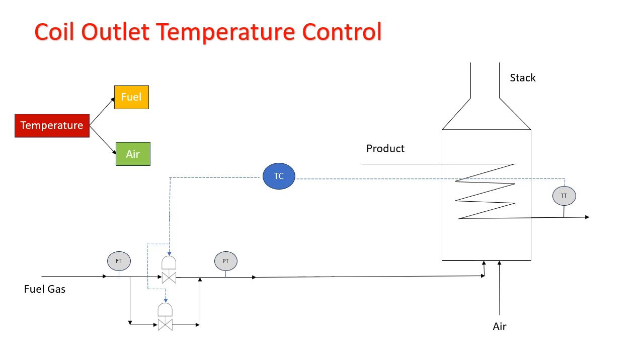As you know, this temperature will depend on how the fuel is burning, right? And the fuel burning temperature depends on two things: one is fuel and another is air. Obviously, there is another parameter, that is the calorific value of the fuel. For the time being, let's consider that the fuel going into this fired heater is always the same kind of fuel, so we don't need to worry about the molecular weight or the calorific value of the fuel.